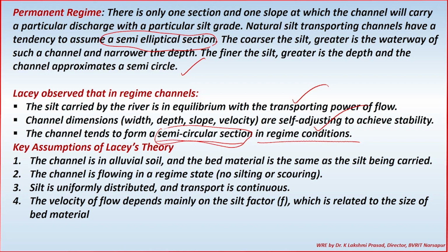Then assumptions of Lacey's theory. The channel is in alluvial soil, right? Bed material is the same as that of the silt being carried. That means whatever water flows from the river into the canal also carries some silt along with it. The silt character is the same as the channel bed and banks material character. Because whatever silt is transported, the moment it is deposited, it becomes alluvial soil.